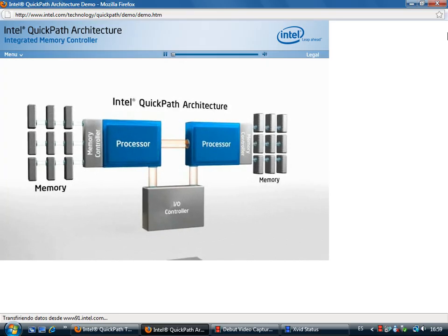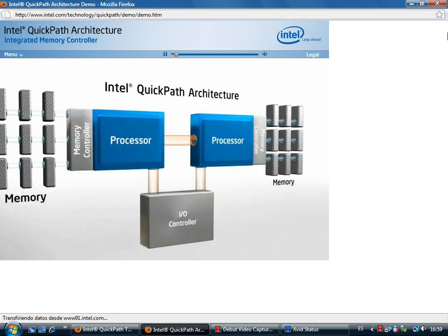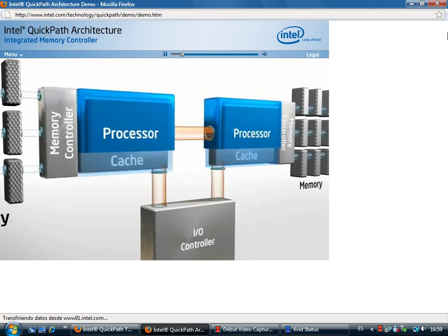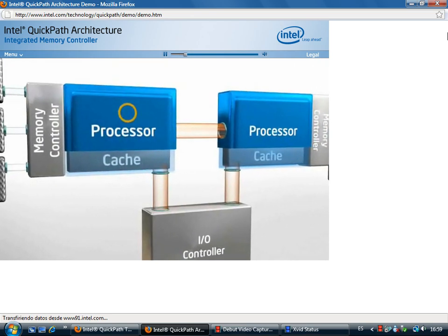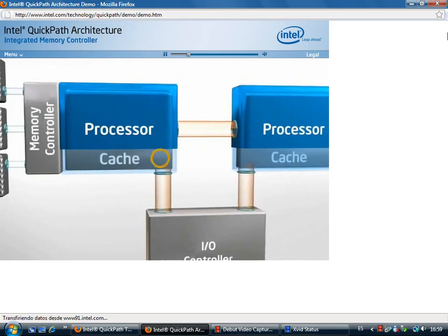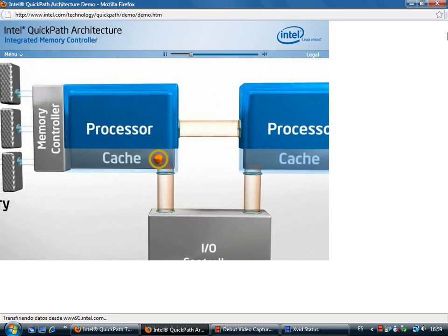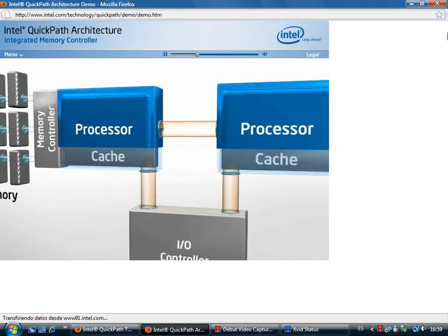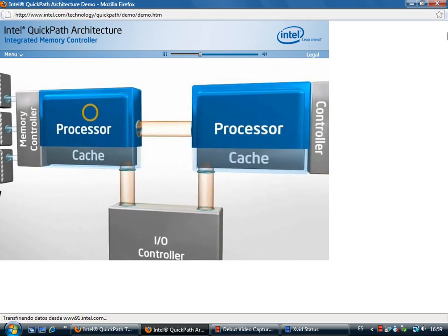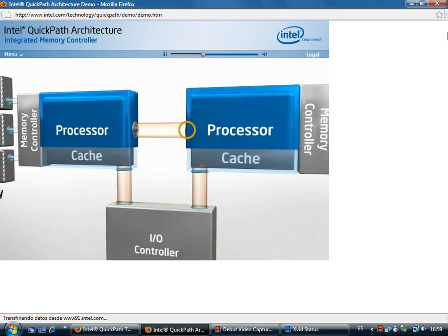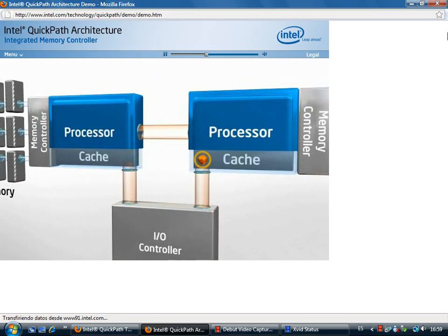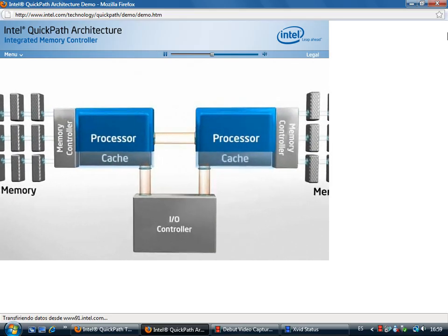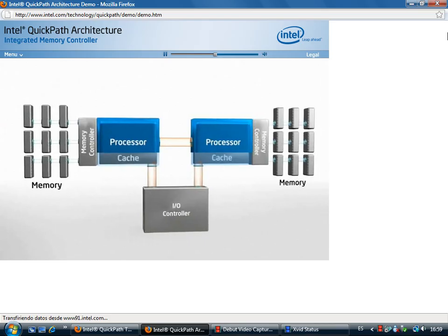Intel has designed a holistic platform solution to speed data movement to applications regardless of the data's location. Preferably, requested data would be in the cache of the processor that's running the application, which is why Intel's next-generation microarchitecture, codenamed Nehalem, features a large, intelligent cache design to minimize latency. The data may also be located in another processor's cache, which is why the Intel Quickpath interconnects were designed to deliver high-bandwidth, inter-processor transfers. But regardless of other efficiencies, data must sometimes be accessed from system memory.